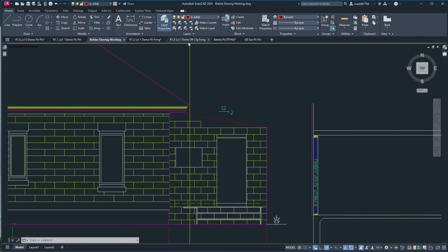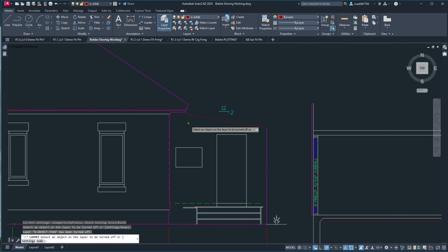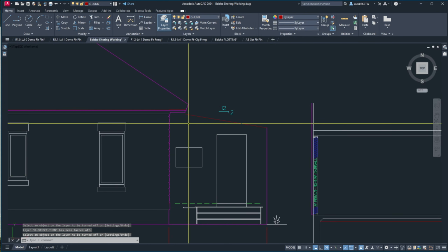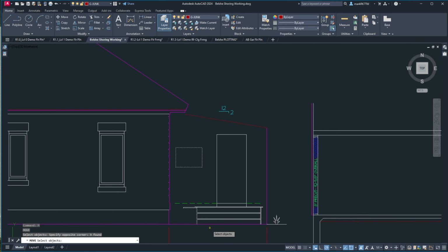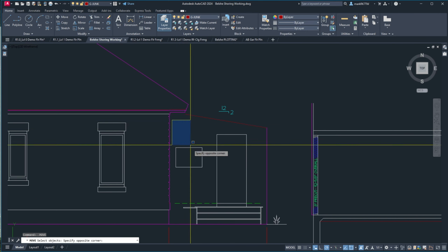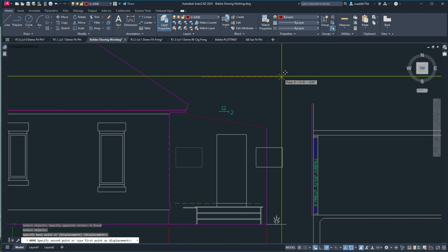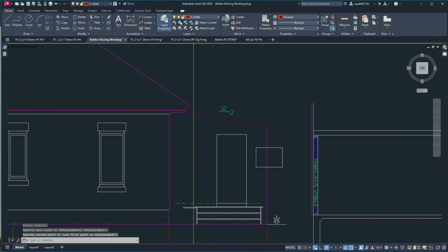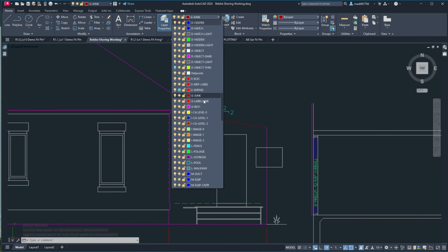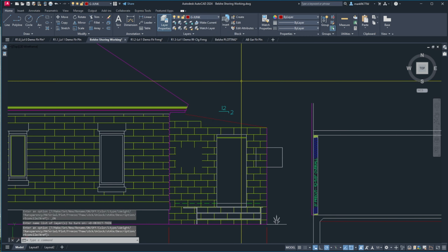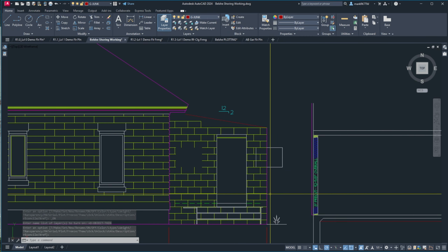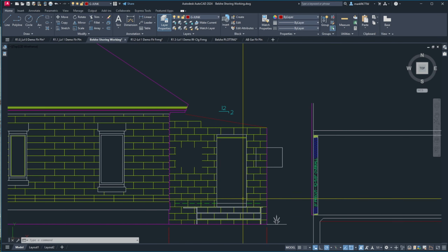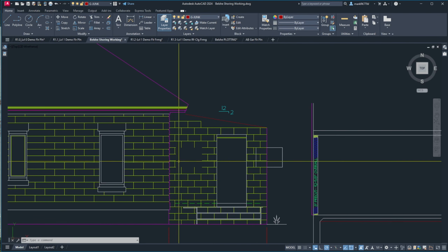So instead of having to go to a list on the side to say freeze a layer, lock a layer, or turn off a layer, I'm going to turn it off. Boom, it's off. Now, if I move these things, let's say I just want to move this window, so I grab it and move it over, and then I go to my layers, hit D to get up there, and boom, turn it on, and look, you have the ability to accidentally grab stuff.